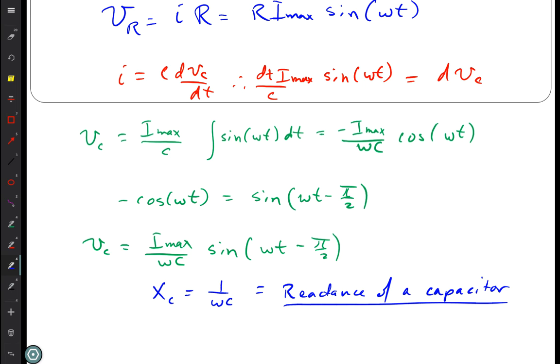Reactance has its name because it's how the capacitor, or as we'll see in a moment, an inductor, reacts to current and voltage. A resistor resists charge going through it. It takes away energy. An inductor or a capacitor doesn't resist, but it reacts to store energy and then give it back. So that's why we have a different word. They're based on actually what happens.